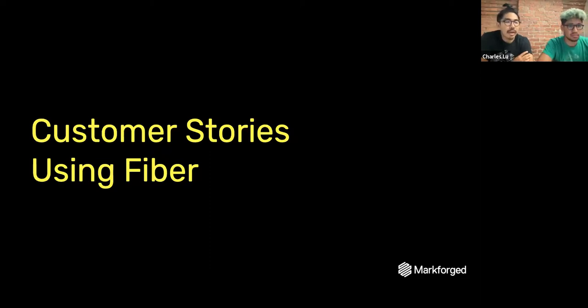I will tell you that the nylon family of materials, so the polyamides, are susceptible to strong acids and bases. So you don't want to submerge in acids and bases, but any sort of solvent, other types of solvents, fluids, even acetone is not going to really do a whole lot to it.